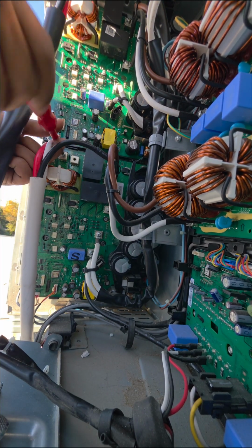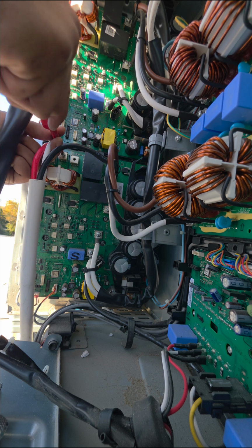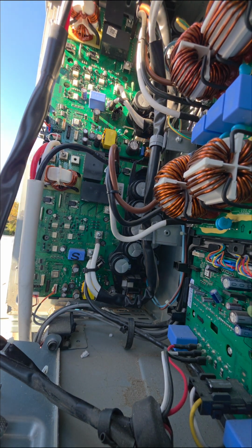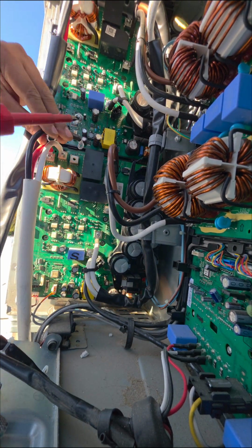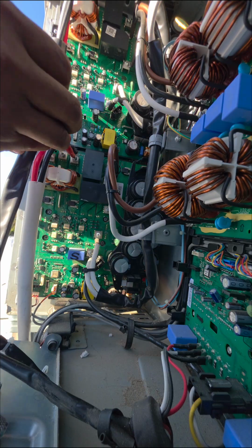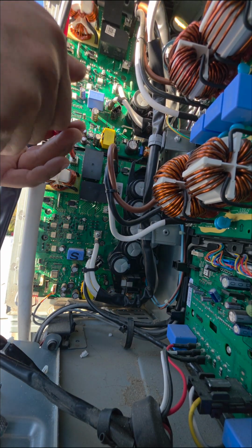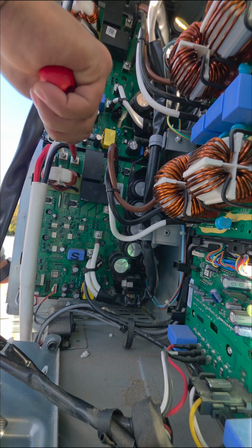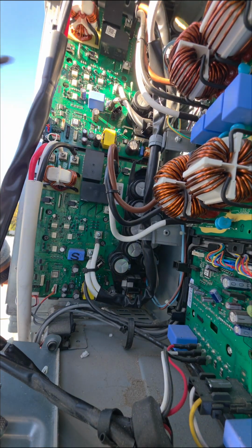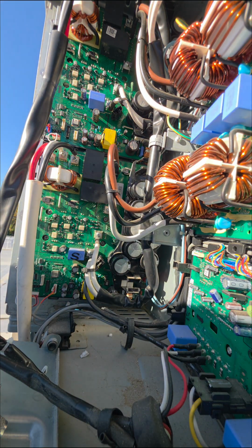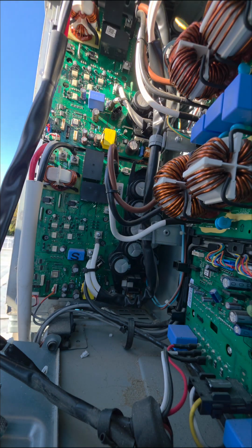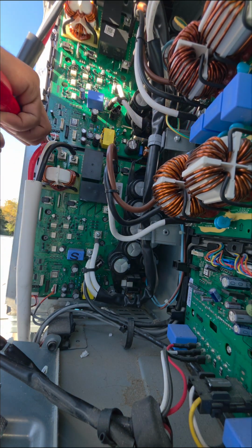But yeah, that's the importance of having clean incoming supply voltage, and that's something that I missed showing, but it is quite important to always verify and establish that you are getting the correct voltage and all your phases are present, in the case of dealing with a three-phase system like we are.